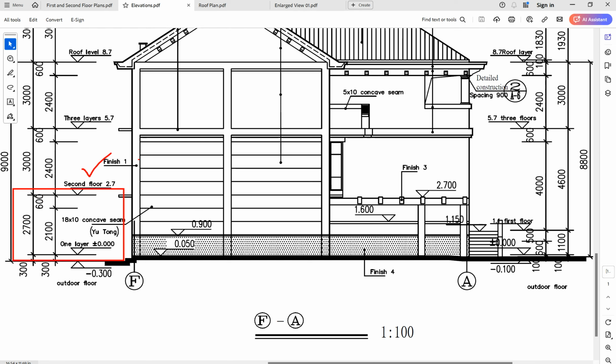So if I do this it is wrong, so I better create this dimension. This is 3.8. So from here you can change this 2.7, or another way is I don't need this. Since you already know 2.7 is from 0, right? So I click this and I change this datum to 2700 and click outside, it will go to 2700. Very simple. It doesn't matter, even if wrong we can change again and again. Don't worry. Okay, this is the good point of using Revit.